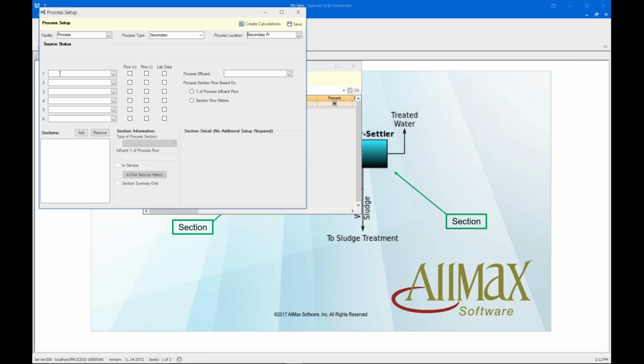If I have an influent flow for my industries, and I do lab and flow there, I can define it. If I have a bypass flow, so maybe I take information out of my main flow and bypass it from the main plant to an equalization tank, for example, we could define that and subtract that flow and pounds and milligrams per liter out, so that I remove those pounds because they're technically not coming into the plant. Again, that just gives you some options.